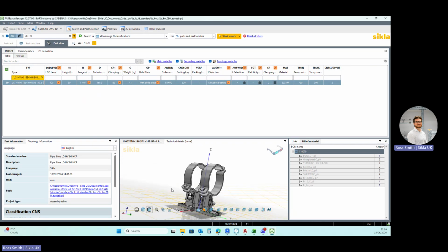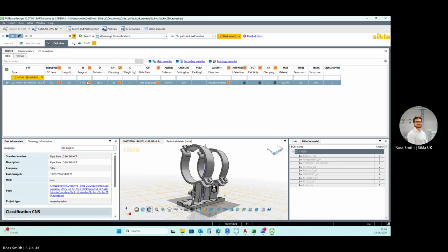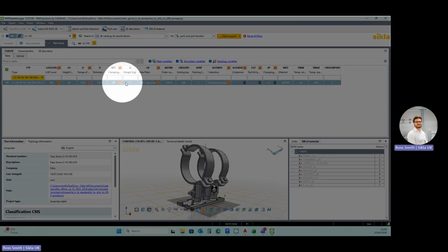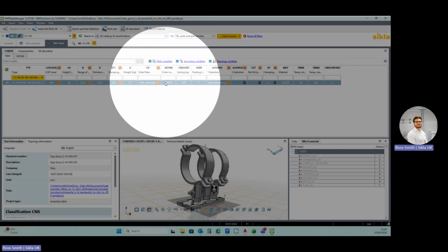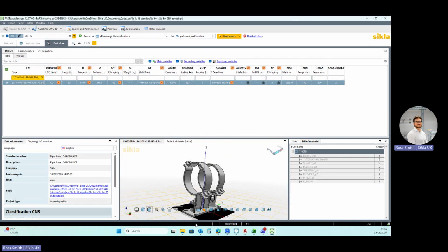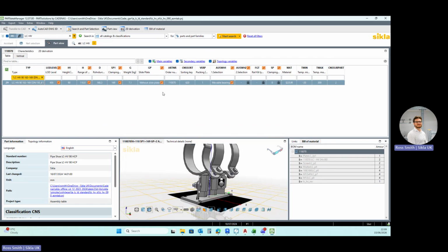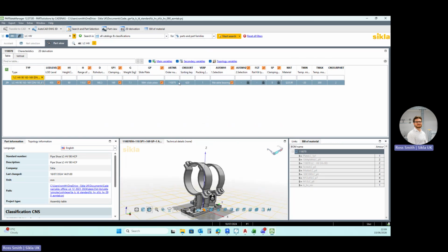Can we see that the part has already and automatically increased its height? Okay. We have other options going along this toolbar to the right. Our industrial pipe shoes are able to have the slide plate removed if we want to use it with some Sikla bracketry, specifically the fixed point. Put that back on. It comes supplied with the plate.